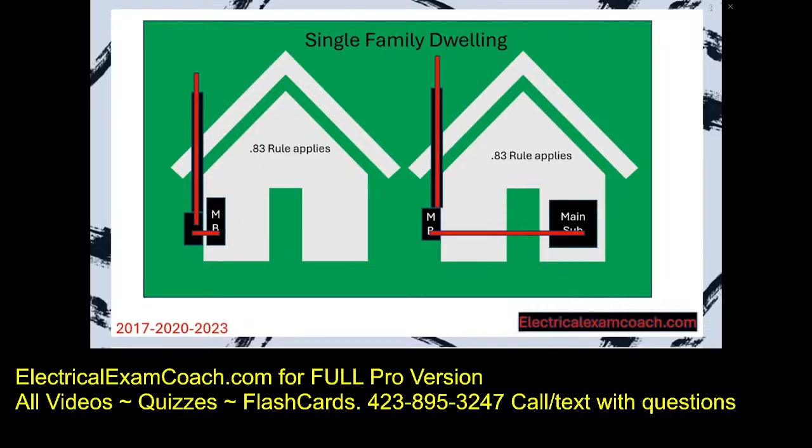So we're allowed to apply it on this one on the left for the whole wire. We go use that table and size our wire based off the table. And the scenario on the right, for all of that wire there for the service itself, and then also for the main feeder, as long as that panel that it's feeding is feeding the entire structure.